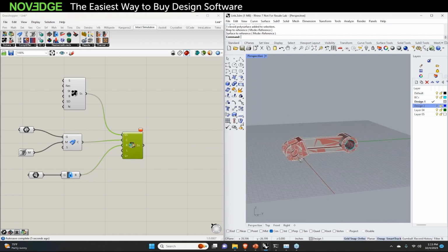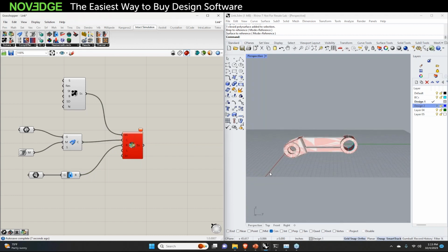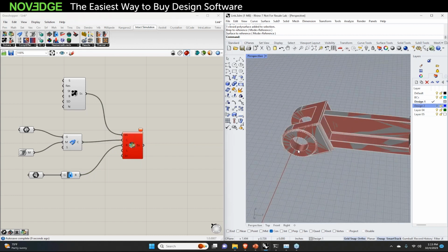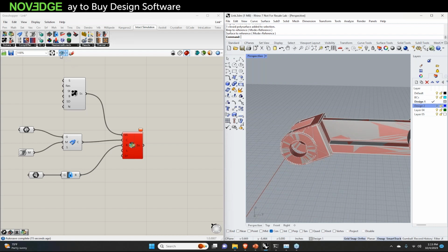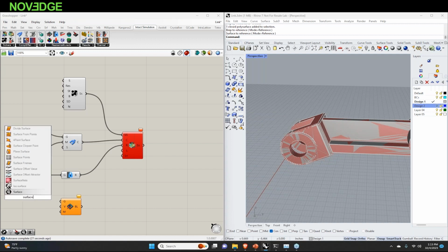Now, we need to specify our loads. Our loads, as I said, we're going to be basically a bearing load pulling to the left on this shape. A bearing load is specified using a bearing load block. We go to the menu, select the bearing load block, add it to the canvas, and the geometry is going to be, again, a surface.